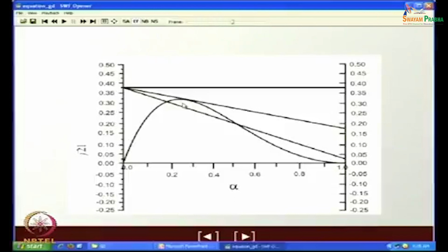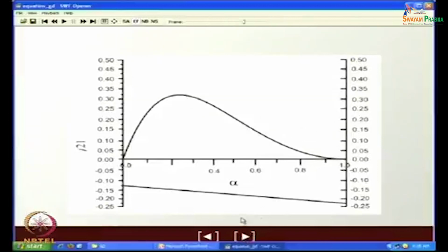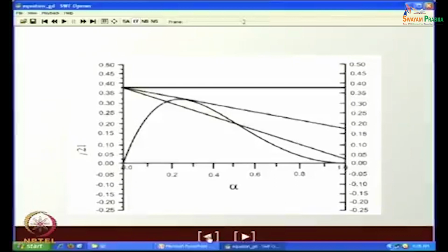Beyond the flooding point, it is not possible. And we found out that for counter current operation with gas down, liquid up, it is never going to be possible. Agreed? And also from this particular curve, we had got an idea regarding an alternative way of constructing this curve, because constructing the straight lines is not a problem.